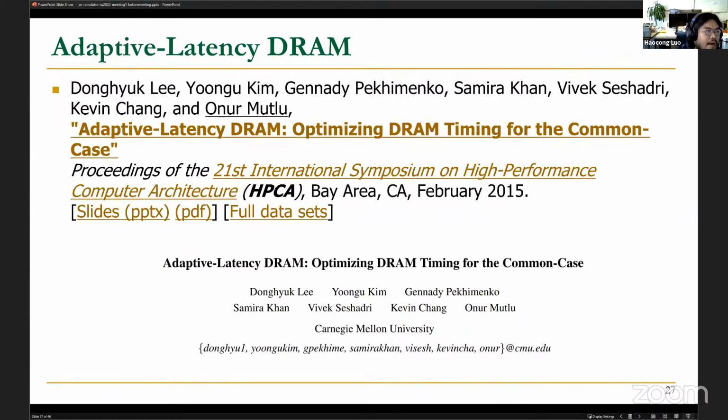And so, besides those previous works that try to modify the architecture of the DRAM chip itself, we also have the following works that do not change the architecture of the commodity DRAM, but instead, through extensive characterization, let's say using DRAM Bender, harvest the operating margins in existing DRAM chips under certain operating conditions.